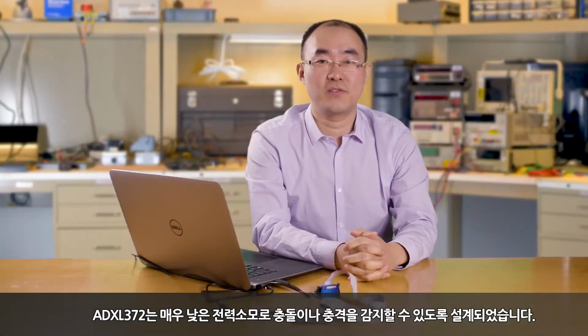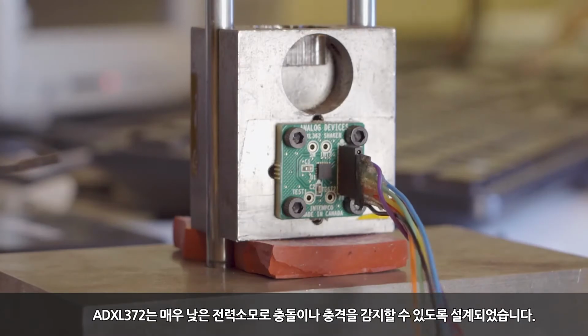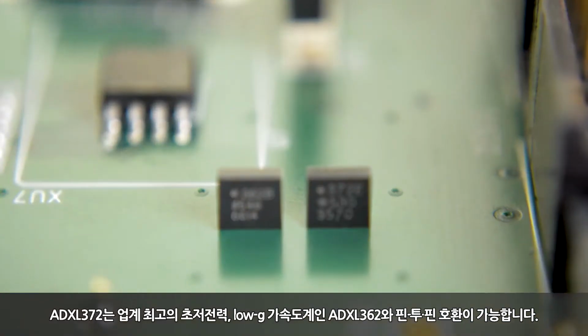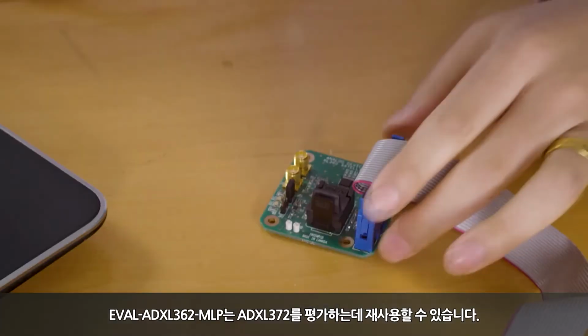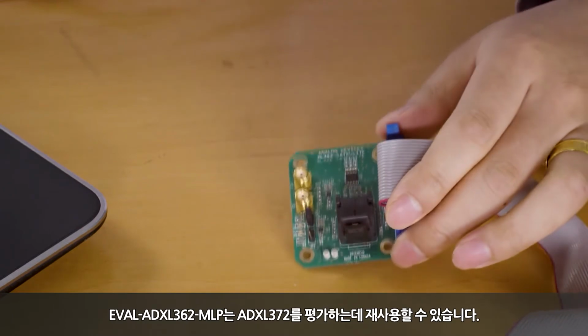The ADXL372 is designed for impact and shock detection with extremely low power consumption. As the ADXL372 is pin-to-pin compatible with the industry-leading ultra-low power low-G accelerometer ADXL362, we can reuse the ADXL362 satellite board to evaluate the ADXL372.